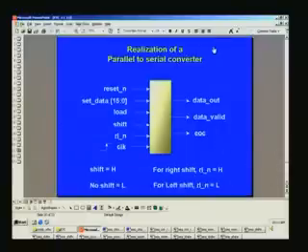We had seen a parallel to serial converter. There is a reset, you can set the data and then load it and then shift once you have loaded. What it does is we have a 16 bit parallel information which will load into the shift register here, and then shift either left or right depending upon this control RLN, one being right shift, at the positive edge of the clock, so long as shift is valid. There will be a data out here which will be a single bit because it is a parallel to serial, and whether the MSB of the data arrives or the LSB arrives depends upon whether it is right shift or left shift.